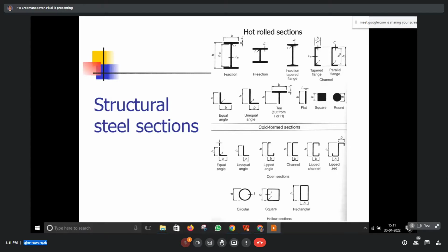A very simple example. This is a sheet of paper. If I hold it like this, it bends like this. But if I fold it like this and keep it in a folded plate shape, this is called the folded plate shape. If I keep it in the folded plate shape, it's much more rigid. The rigidity modulus of the shape, not of the material, increases a lot.